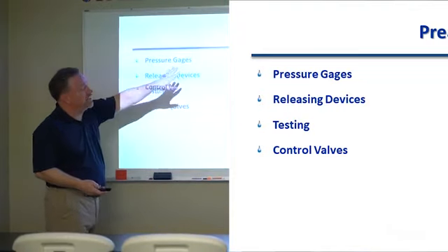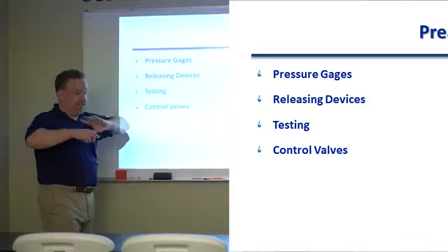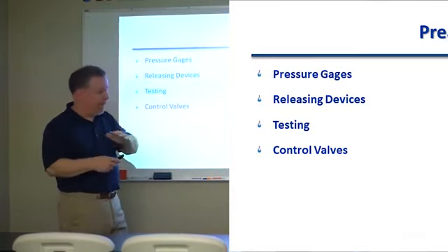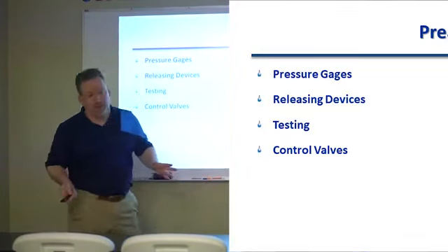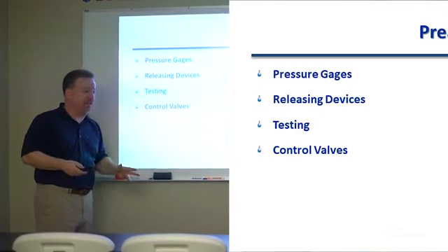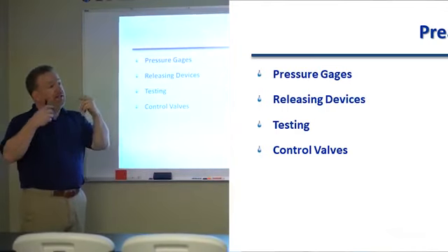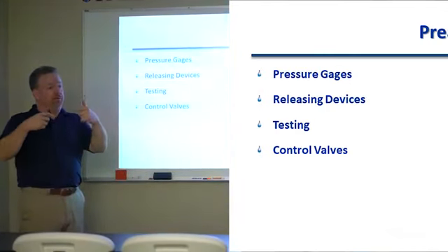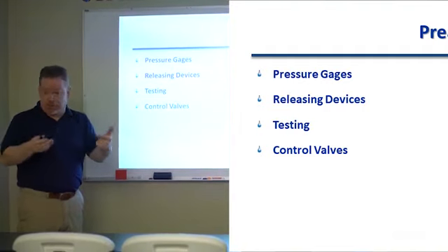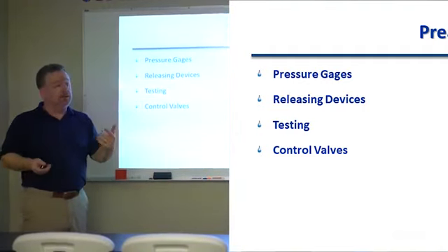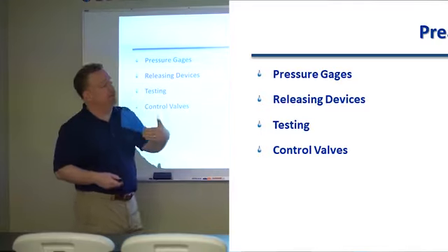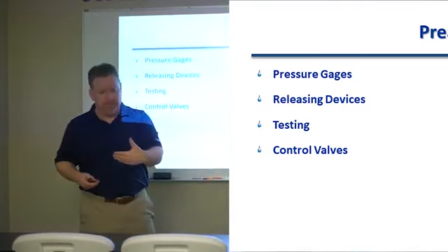So the pre-action system basically is a closed system. All the sprinklers are in place. You wouldn't notice anything different about the system necessarily. It's just that it operates as a dry system. There's no water in the piping. It operates interactive with the alarm system.